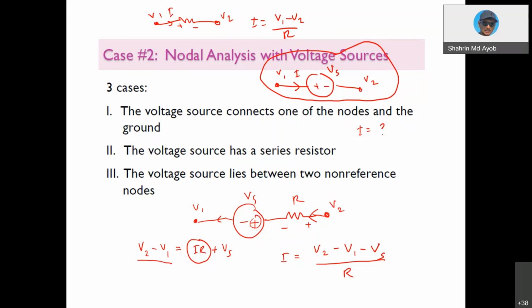You cannot change it to a resistor, because a resistor absorbs power, but right now the voltage source is actually supplying energy into the circuit. You cannot model the voltage source with a resistor, right? If you model it as a resistor, it absorbs, it cannot generate. So we cannot transform the voltage source into an equivalent resistor.